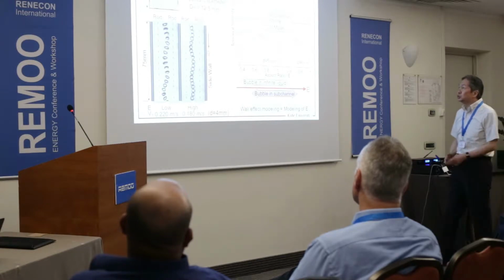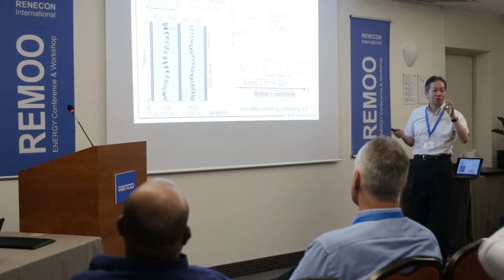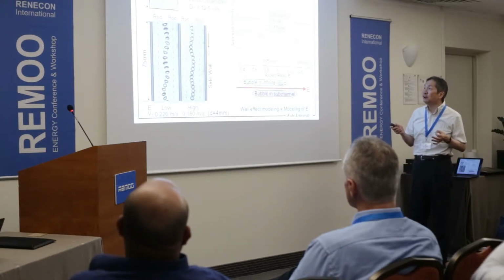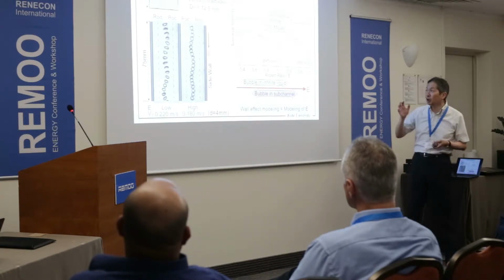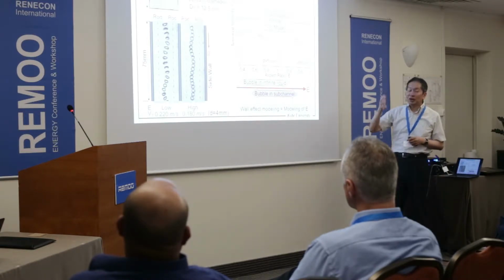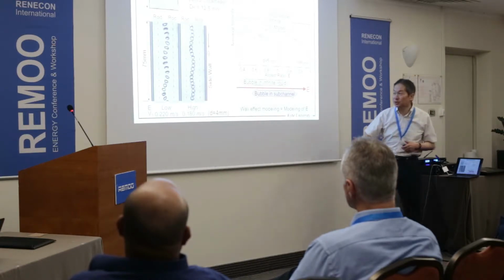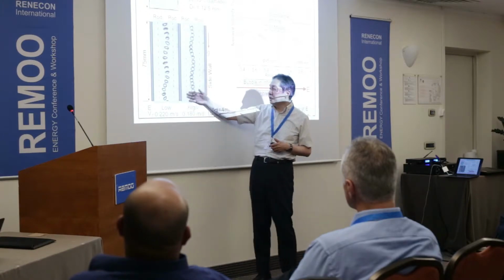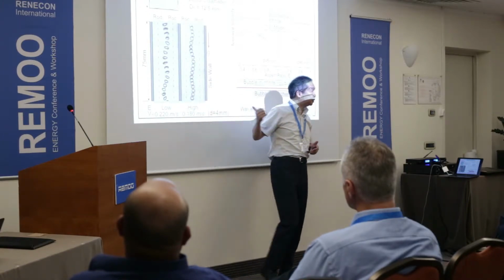Then we also measured using this 2x2 rod bundle geometry, using a very special material for the rod. This is FEP tubes, fluorinated ethylene propylene, and it has the same refractive index as water, and it's transparent, so that you can observe the flow even in the backside of the rod without any optical distortion.